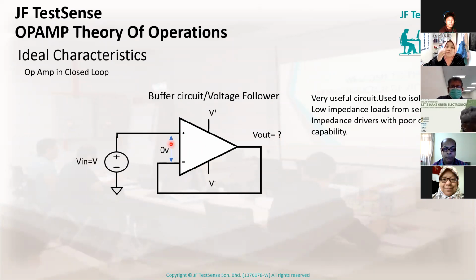You can't load a high resistance output device. Otherwise, the voltage that device produces will be low when it goes to a low impedance instrument, right? I will show that in a bit more detail.